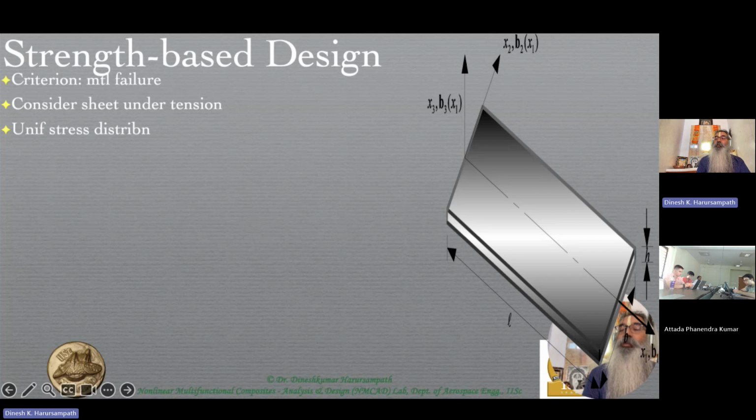Thanks to Saint Venant's principle, it's proven that if you go slightly away from the border, that is, this is x1 equal to L and this is x1 equal to 0, the extreme cross sections, then if you're a little into the interior from those two ends, you'll see in all of these highlighted portions that it really doesn't matter how the actual load is applied at the two ends.